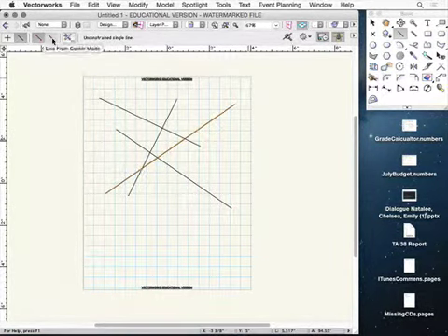I'm going to say my control offset, I want my control offset to be 1/8 of an inch. Okay, create lines. Okay, and that adjusts things. Okay, anytime you see the pencil and the wrench, click on it. It will allow you to set things inside of it for the tool. I can also do constrained lines where I can only draw up and down and side to side. Okay. Again, double lines are not particularly useful for drafting scenery, so they're another tool that I show in class and then never show again.